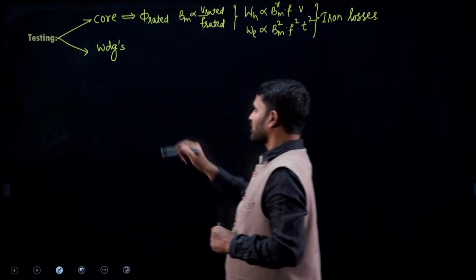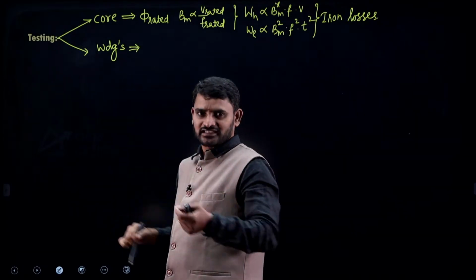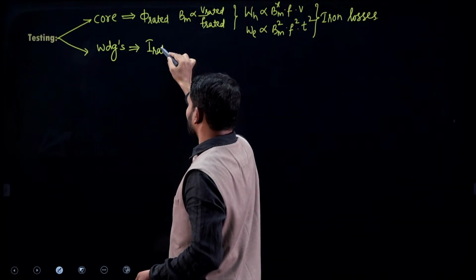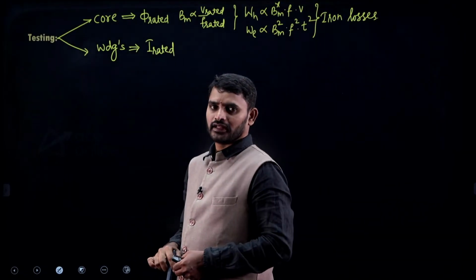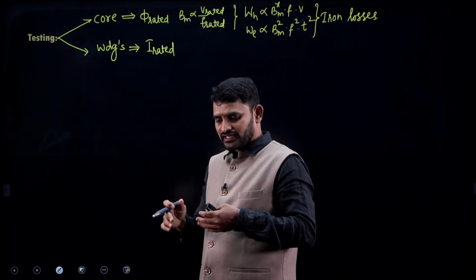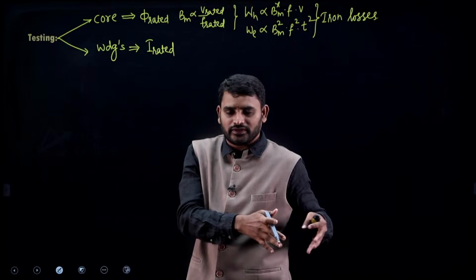Okay. Now coming to the winding, I want to test whether the winding is carrying rated current or not. The winding's purpose is to carry the rated current. Now to circulate rated current, we generally have to put rated load.